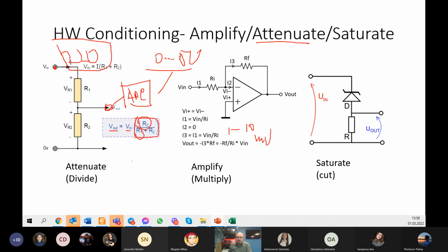It's not enough for the ADC because the resolution is about 4 millivolts per division, and in this case the minimum will be 0 and the maximum will be 2 or maybe 3 out of 1023. The error will be about plus or minus 50%.